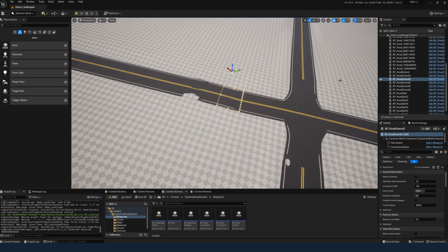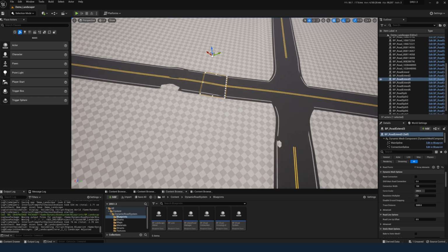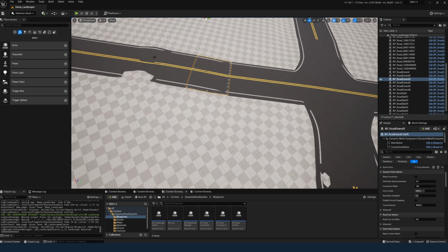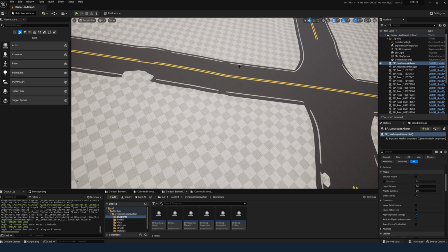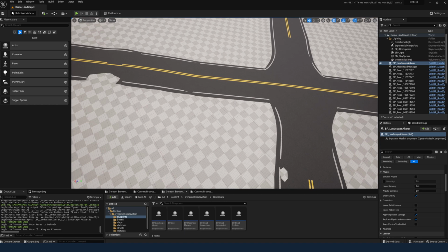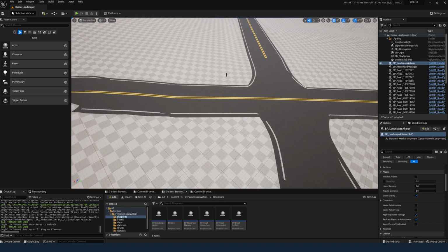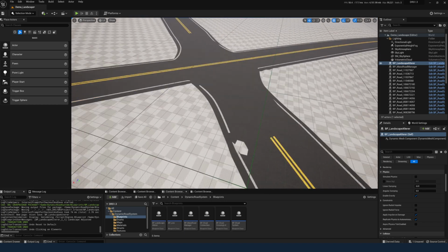You don't want to have to do this for every road, so you may have to go into the Mass Road Manager blueprint and press Update All Roads. Alternatively, the road connections would update if you were to close out of your project and then open it back up. I tried having it update all the road connections in the blueprint right after the alteration finishes, but the dynamic actors are being tricky, so you will have to use one of the methods mentioned before.